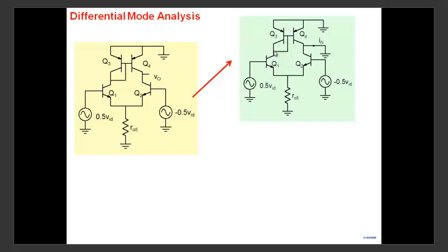So whenever you have a very small resistance, what is the value of the voltage that will develop here? Current is flowing through the resistor, so I'll have a value of voltage. But if the resistor is very small, the value of the voltage will be very small. So our assumption is that the voltage at this particular point will be very small. Very small means that this node is very close to ground.